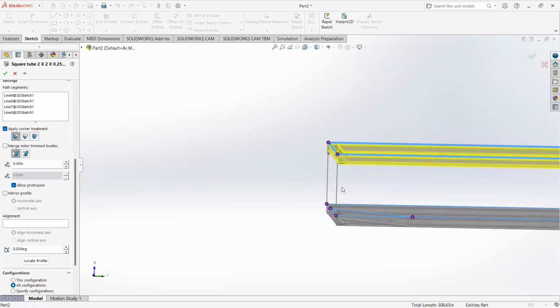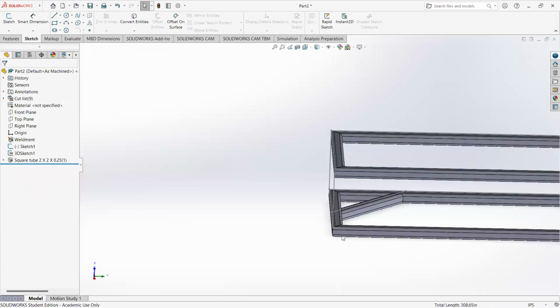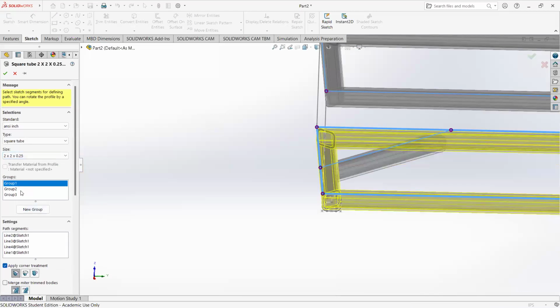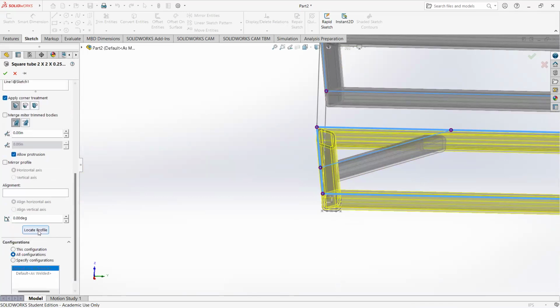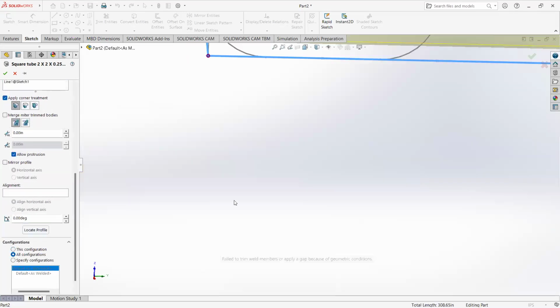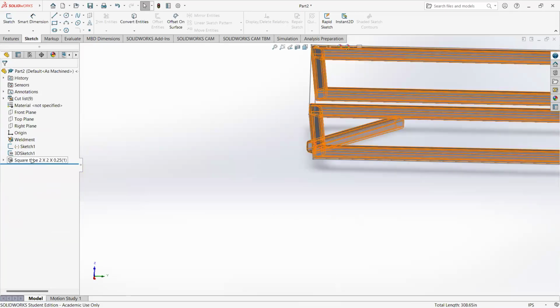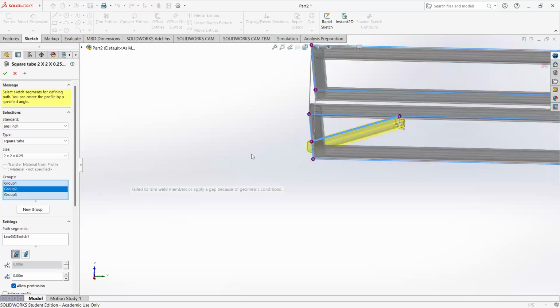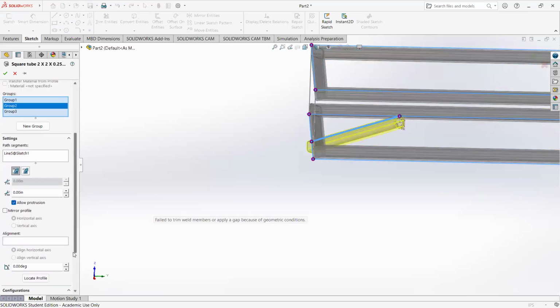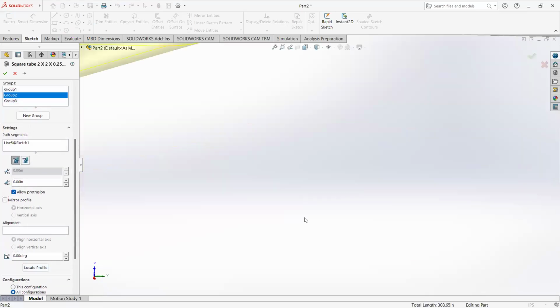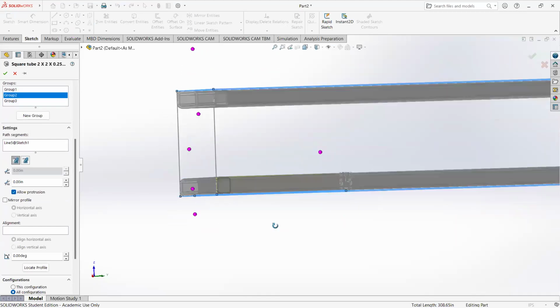So if I wanted this whole table, whatever this is, to be 12 inches tall, I would have to modify the first group. So let's do that while we're here. Edit, and I can always go back and change groups. So I'm going to change this group, locate the profile, and choose this lower dot instead. I need to do the same for group number 2, that little brace, and locate. And grab that center point at the bottom. This now is flush with the bottom instead of flush with the top.